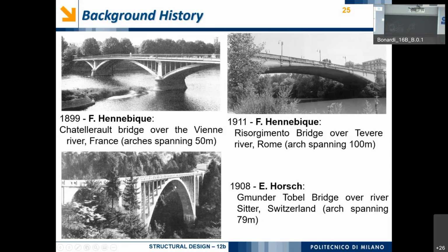It is very interesting to look at bridges because when we look at the bridge, we only see structure. We do not see anything else that can prevent us from understanding the structural behavior. In this case, for example, we have the arch, and obviously the arch works in compression. Then we have these other elements, these columns, let's say, which transfer the load from the deck of the bridge to the arch.